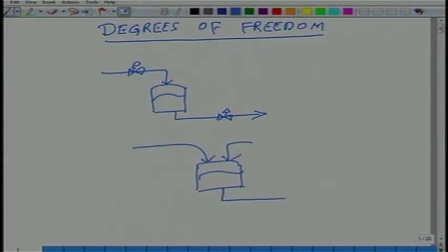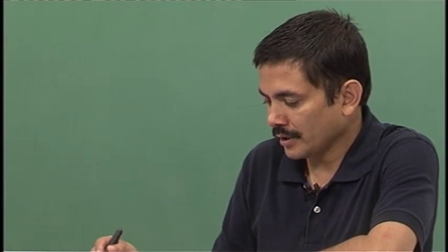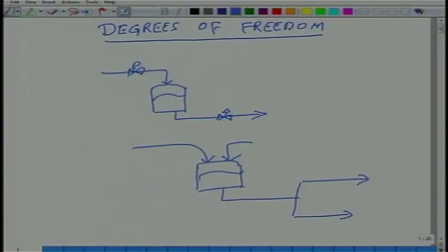Let's say I take an outlet stream and I split it into 2. Stream 1 is feeding a process train. Stream 2 is feeding another process train. How many independent valves can I put on the outlet side? Only 2, right, because incompressibility dictates that.